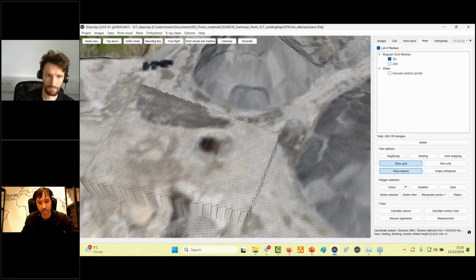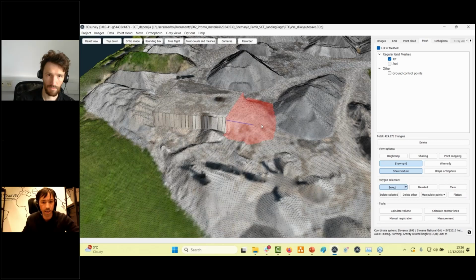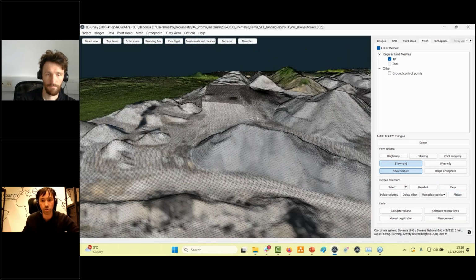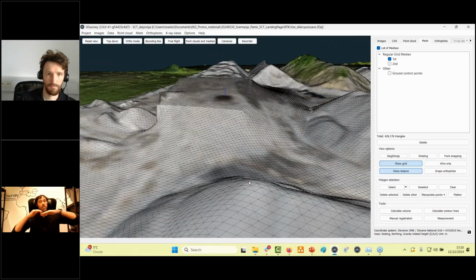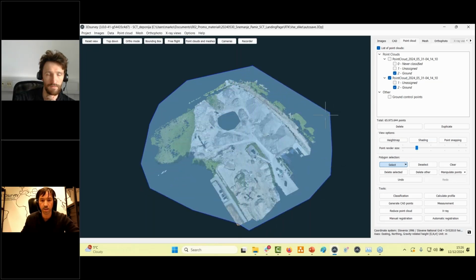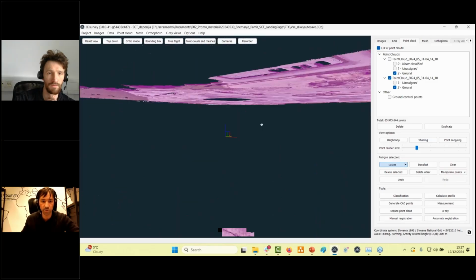So when I have something like that, I can maybe make it more fluent with flatten in a way like that. So you can play with this limitlessly. Okay, and create your design surfaces for the new volumes. Or if you need to calculate the surface from a specific height, you can go back to the point cloud. I will take this already modified point cloud and give my height here, so 286. For example, if you need to calculate volume from some specific plane and a realistic surface, select all your points, set the height to, let's say, 290, and immediately move all the points to a specific plane, like you see here.